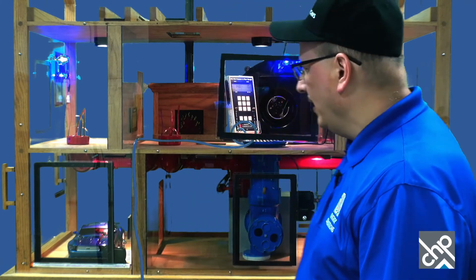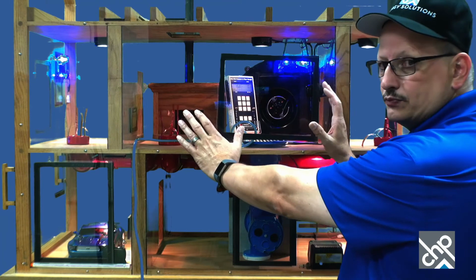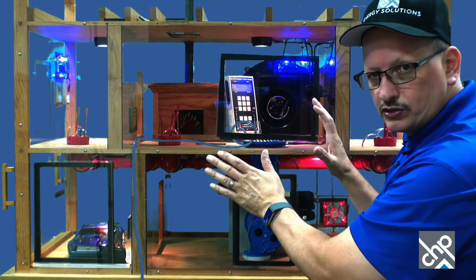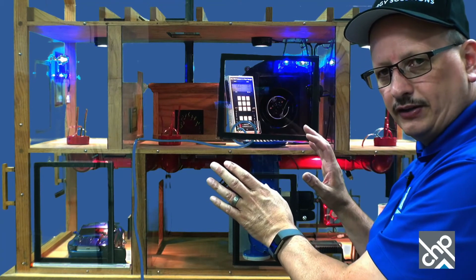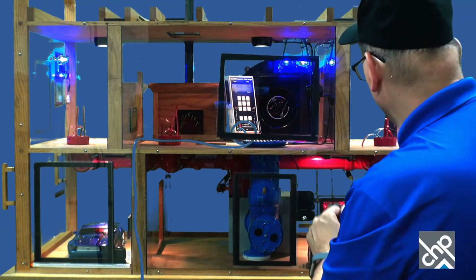So you would get it into this worst case. Whatever made your most negative number, you go back to that situation. If the worst case was just with the exhaust fans on and the air handler fan wasn't on, then you would go back to whatever made that most negative number. But in this case, this is our most negative number. And a big part of that is the central return and all these doors closed, and doing some pressure relief might help as well.